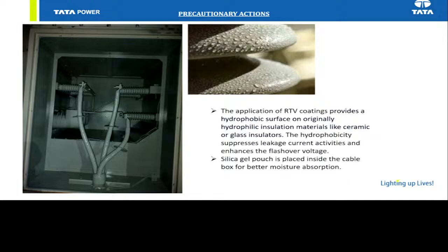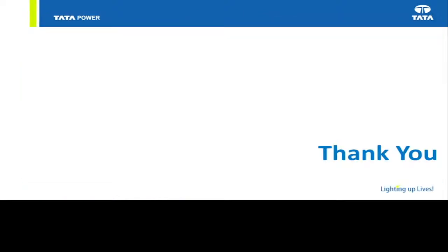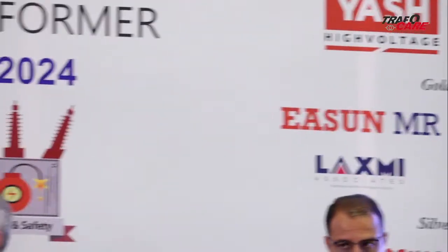This is a good maintenance practice which we have followed. We have now completed this silicone coating in almost all sites, and the issues of flashover inside the HT box have been reduced by a huge margin. I don't have that data right now, but there is no tripping as such because of flashover inside the HT panel.